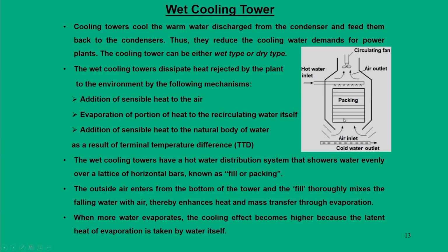So, when air gets in contact with this hot water, it absorbs heat, that means its temperature also increases, but the water vapor concentration in this air keeps on increasing until it gets saturated. Once it is saturated, it cannot absorb further moisture, but as it goes up and again comes in contact with water, its temperature goes up. So it keeps on soaking up the water vapors from the hot water. Through this process, at the end of this outlet, we get air which is almost heated and saturated. That means air doesn't have any more tendency to absorb moisture from this water.